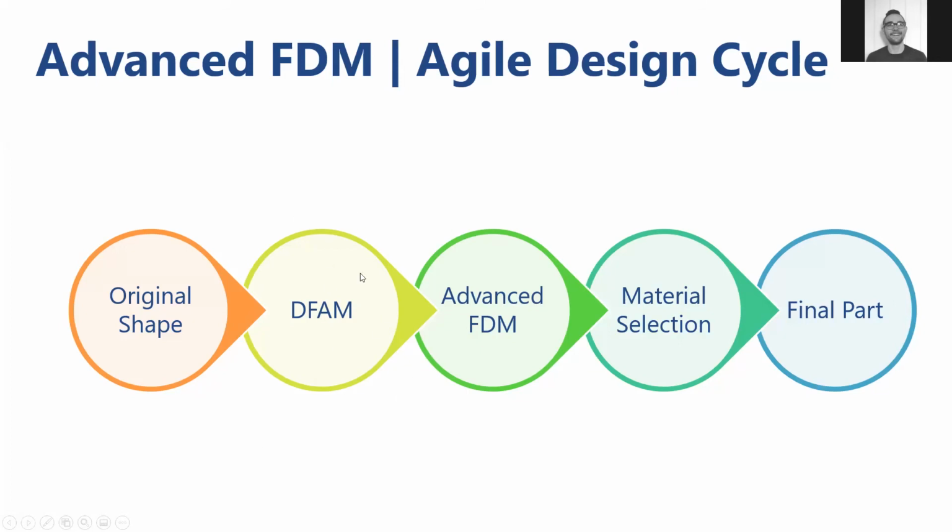And again, those that are more experienced with additive would likely be thinking ahead, okay, I'm likely going to print the solid, want to save on materials. Once I get my near net shape, let me do an FEA analysis and see where I'll need some reinforcement bars, put that into the CAD and the original design phase, and then pop straight into advanced FDM.